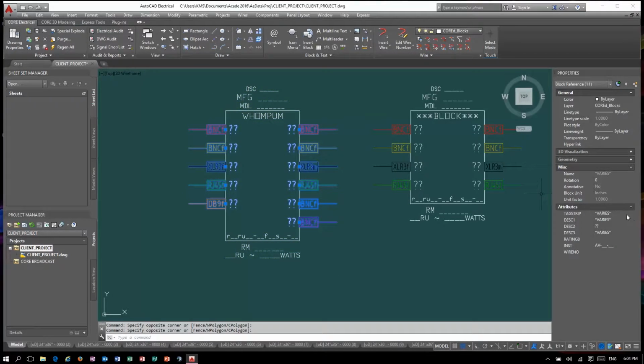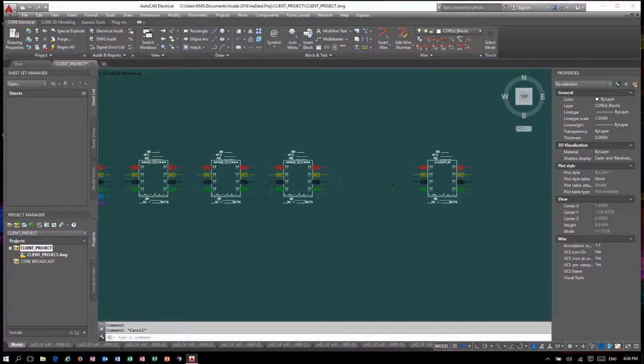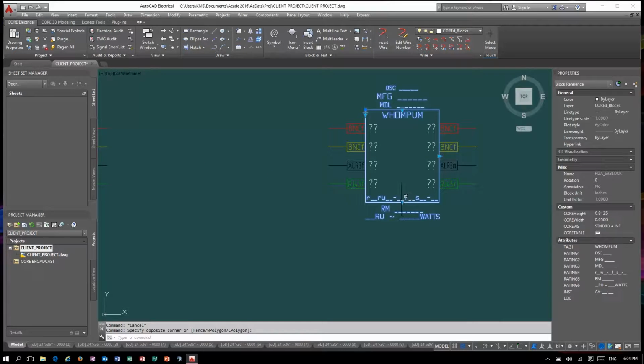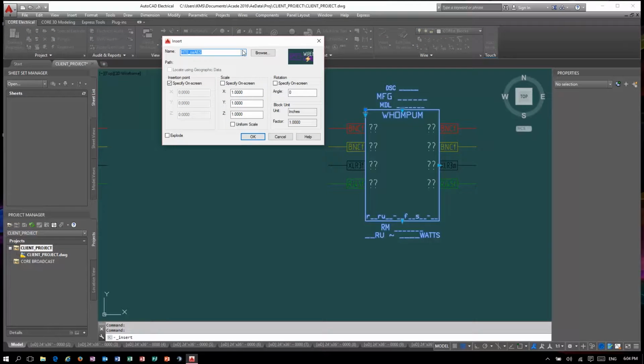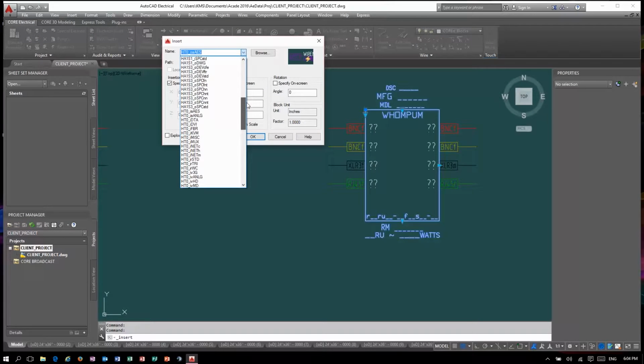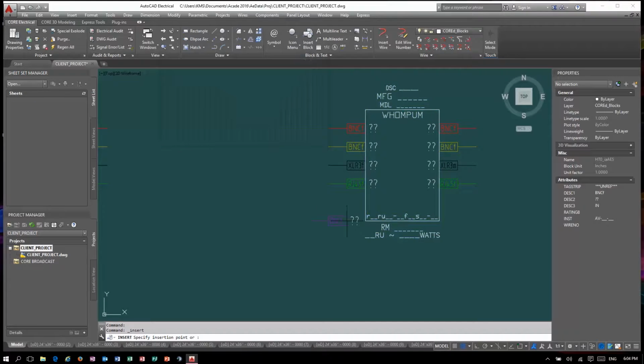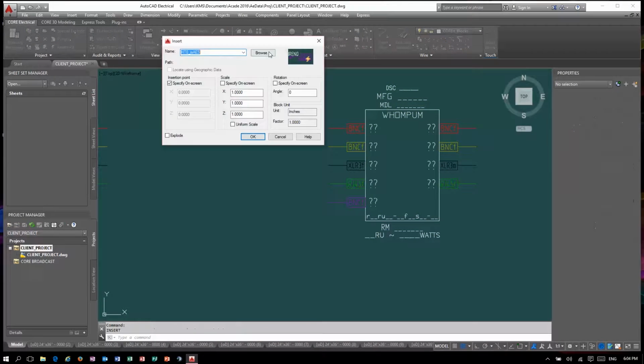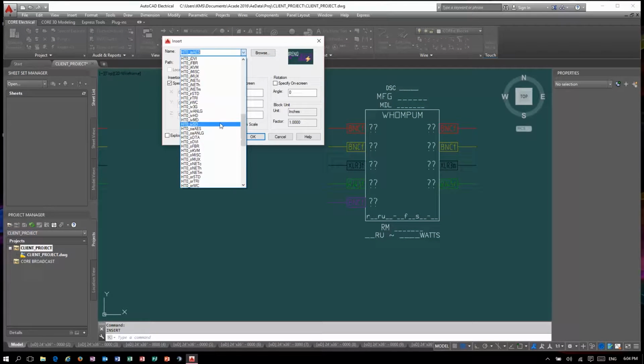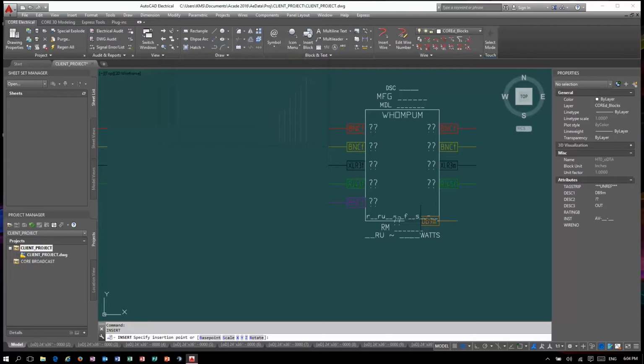It then analyzes the project level, block level, connector level, and wire levels associated with those devices using an advanced multi-layer algorithm. It identifies incompatibility of signal types like digital outputs into an analog input, high definition or ultra high definition into a standard definition device, and configurable multi-definition into various fixed standard devices.